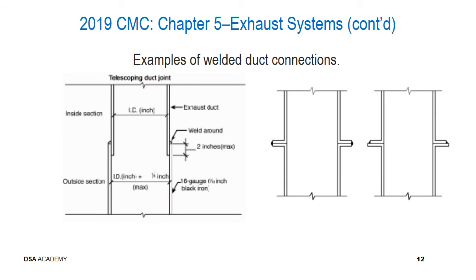As an alternate, the images on the right show flanged joints, and a couple varieties for actually welding the flanged joints. The one on the left is basically depicting a situation where you're going to weld the joints continuously, obviously all the way around, and it's more of a butt configuration, but not necessarily a butt weld, of course.